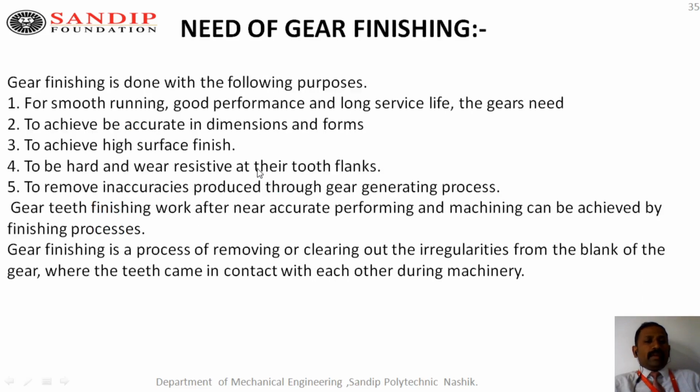Now next, this is the last topic: gear finishing. Before this we learned how to manufacture gears, and after manufacturing there is a need for finishing. Why is finishing needed? Because gears mesh with each other, so to avoid noise, for quiet operation, and to reduce the wear and tear rate, finishing is required.